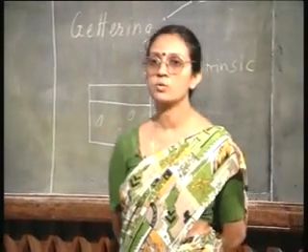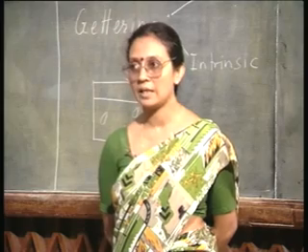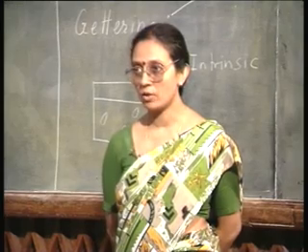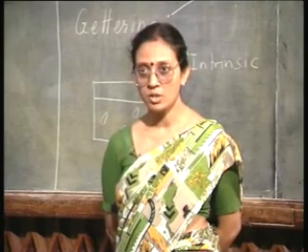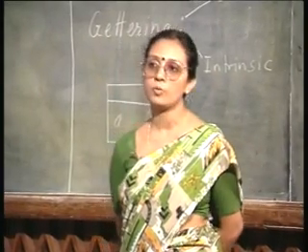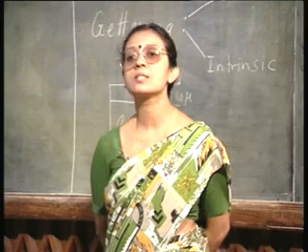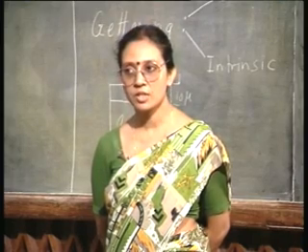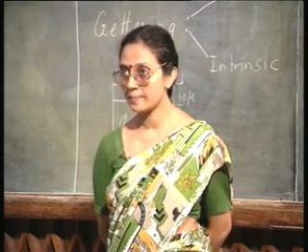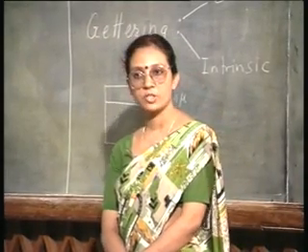In order to make an NPN transistor, we started out with a p-type substrate, and then after the buried layer diffusion, we had to carry out an epitaxy in order to have the N region grown on top of this p-type crystal, an N crystal grown on top of the p-type bulk crystal, and the actual device was housed in this epitaxial portion, not in the bulk crystal. Remember? So, just having this bulk crystal may not be sufficient for your needs.